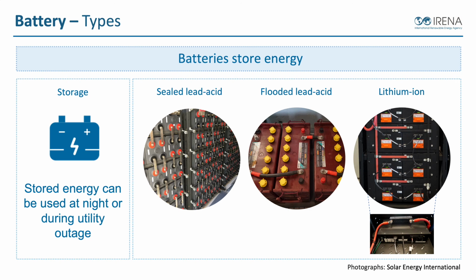So a sealed battery means that it doesn't have anything to do internal maintenance on. There's no checking of liquids. So it's all sealed up. We need to do maintenance on the outside to make sure we don't have corrosion, but everything's sealed into that battery itself. And that's why we can see these batteries are mounted on their side with the terminals facing out.